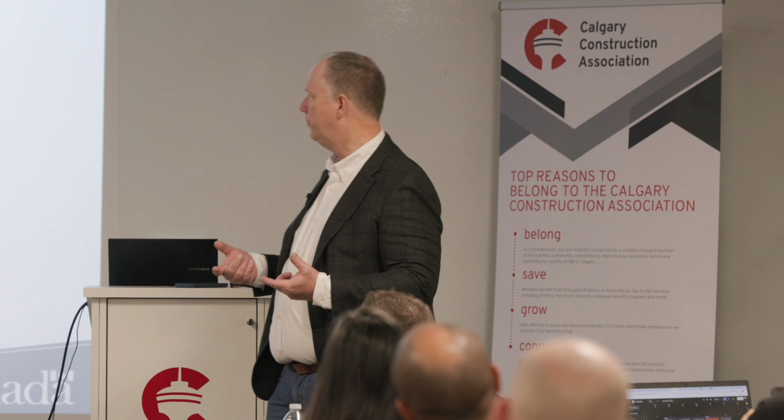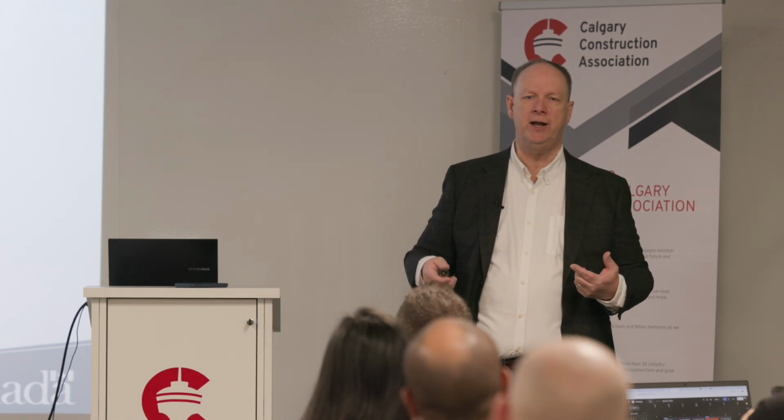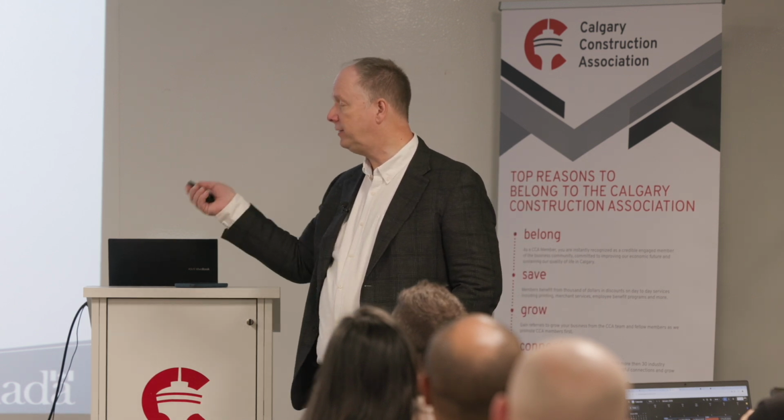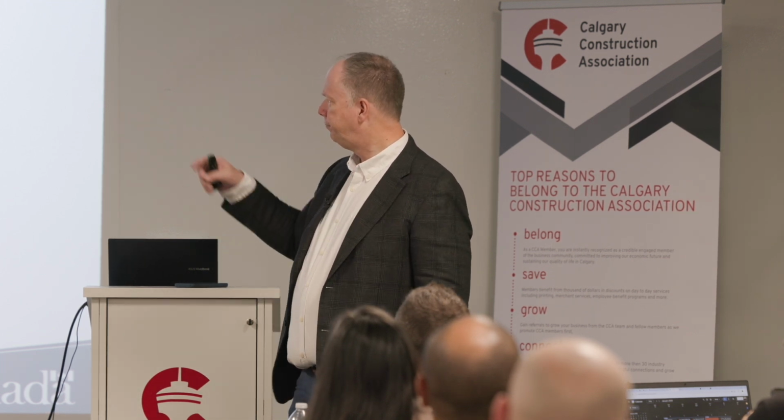Okay? So again, the Master Planning and Decision Guide has more details on this sort of thing, but I'm a big fan. The great thing about mid-velocity, I don't know of any current furnace manufacturer that doesn't allow for that kind of operation. So we don't have to change any equipment. When we get into high velocity, because we're dealing with a high static pressure, we do have to change the equipment a little bit. And it becomes proprietary. The ducting becomes proprietary. Your mid-velocity, you're dealing with 3 and 4 inch metal smooth edge ducting. There's nothing strange about it. We can get it from all of our suppliers.